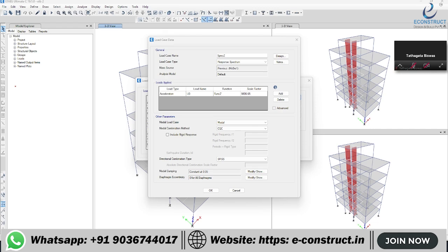Now if you want to split it, in that case you take I by 3R over there and keep this one over here. Whatever this value will come, let's say Z is 0.16, divided by 3 into 2.5, whatever this value will be, you multiply with G and put it as an initial scale factor. Then you run the analysis.